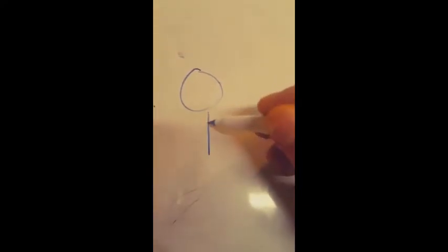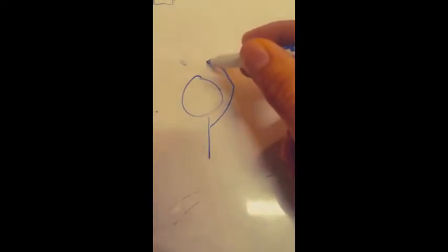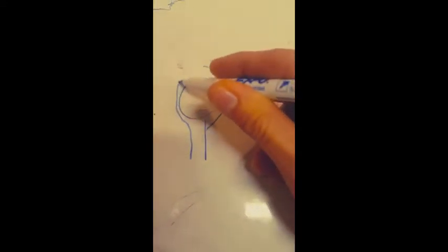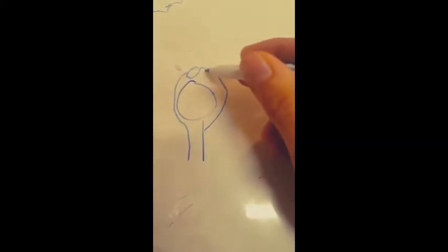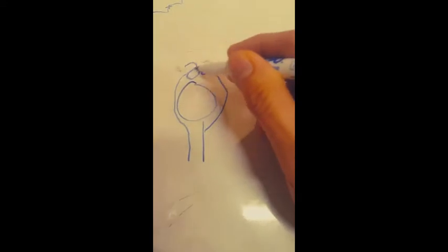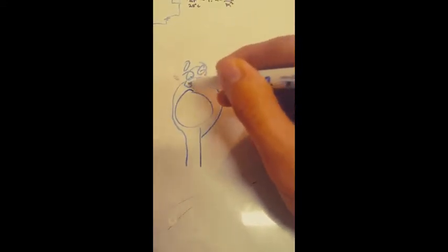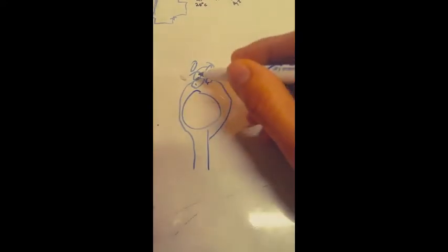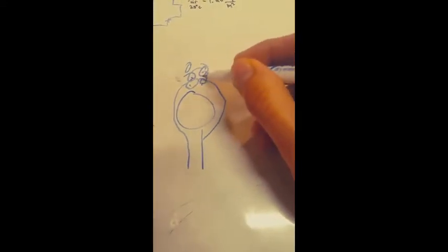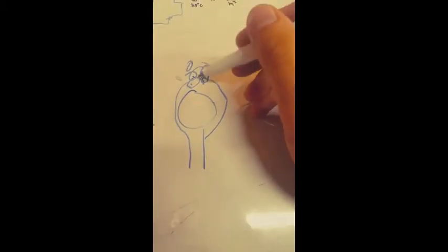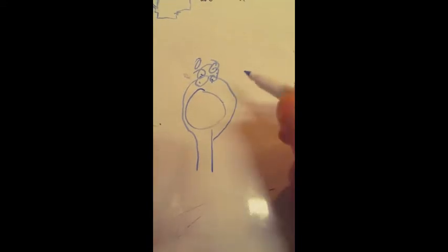What actually happens is the air flows and comes around the ball, and when it hits the air on the other side, it creates vortices. Inside of the vortices are low pressure pockets, and those low pressure pockets are what creates the low pressure zone on the top of the ball.